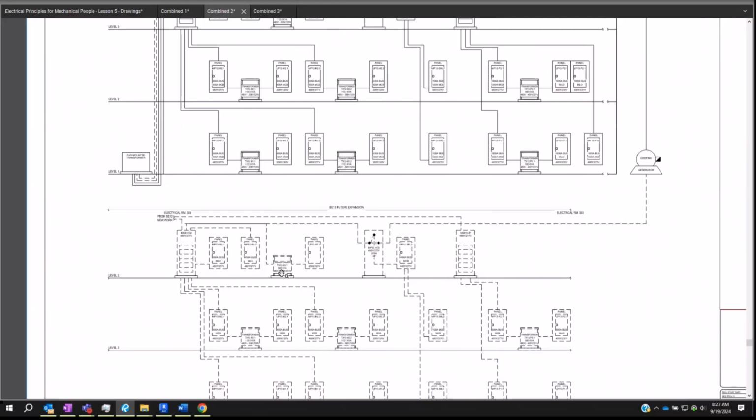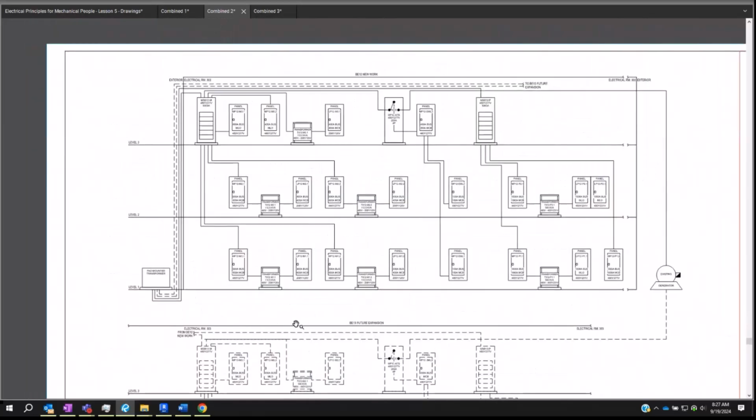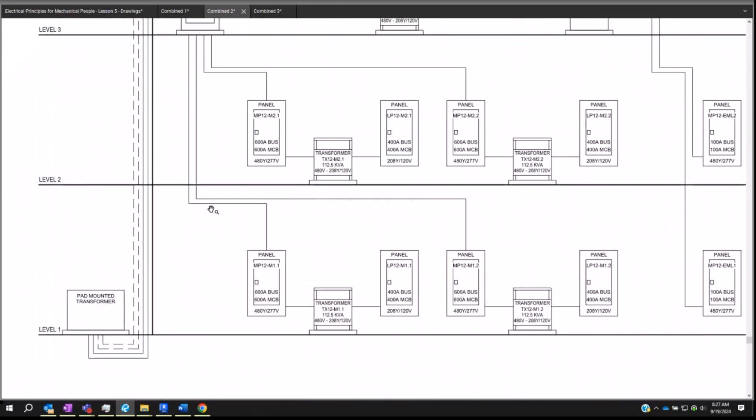Is it a good way to put it that the riser diagram is how the big equipment is wired up, meaning what's attached to what, but then the single line is the details, like the wire size of the panel going to the transformer, more detail of this?